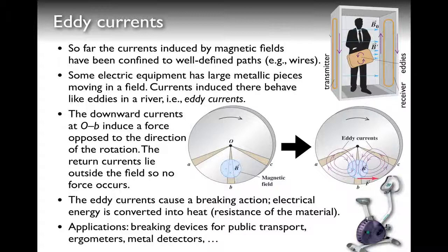Finally, another system that actually uses this type of technology, however in a very different way, is the TSA security gate. In that particular case, you have a transmitter and a receiver. The transmitter sends a magnetic field out. If you now have some metallic object in your suitcase, this will produce eddy currents that produce an additional magnetic field. The receiver is tuned to only measure the transmitted magnetic field, meaning that it can detect the additional field due to the eddies, and therefore it will give a loud beeping signal, and you'll have to go to secondary screening, strip all the way down, bend over, and be very, very unhappy with the TSA officers.